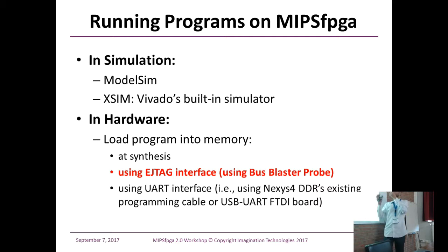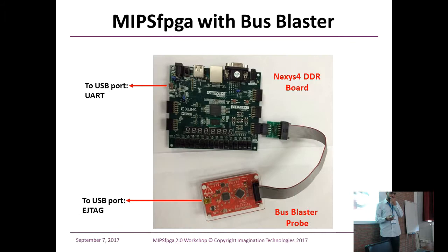In this workshop, we have bus blasters. You all have the red board PCB, so we're going to use the JTAG interface. But all of these ways are documented in the teaching package. If you want just simulation, you can do it. If you want to do synthesis or UART, you can do this. In the workshop, we're going to use the JTAG interface. This is how the bus blaster is wired to the Nexys 4 DDR board.